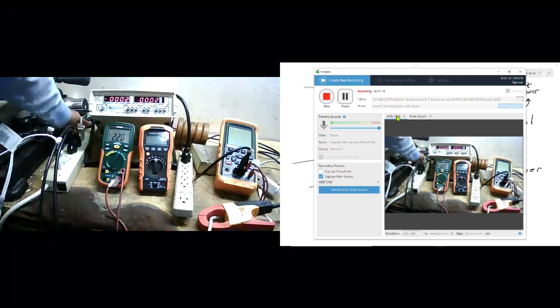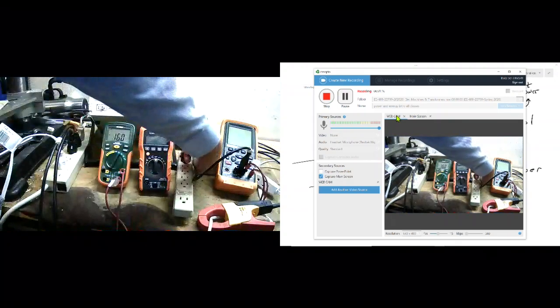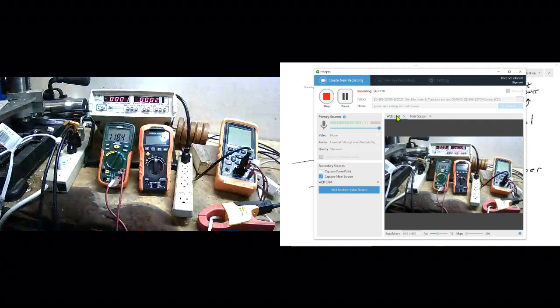When I turn everything back on, the instant I turn it on, it goes up to 180 plus watts. When I turn the drill press off, it goes to zero. On, 186. Off, zero. Power's instantaneous. It's what that drill press is drawing right now.